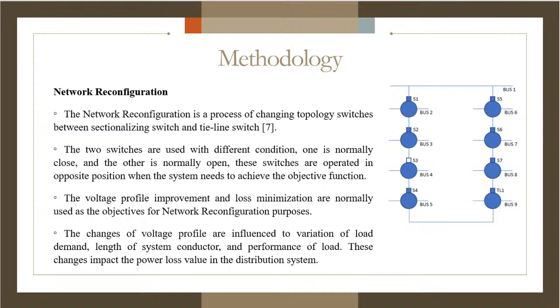The voltage profile improvement and loss minimization are normally used as the objective for the network reconfiguration purposes. The changes of voltage profile are influenced by variation of load demand, length of system conductor, and performance of load. These changes impact the power loss value in the distribution system.